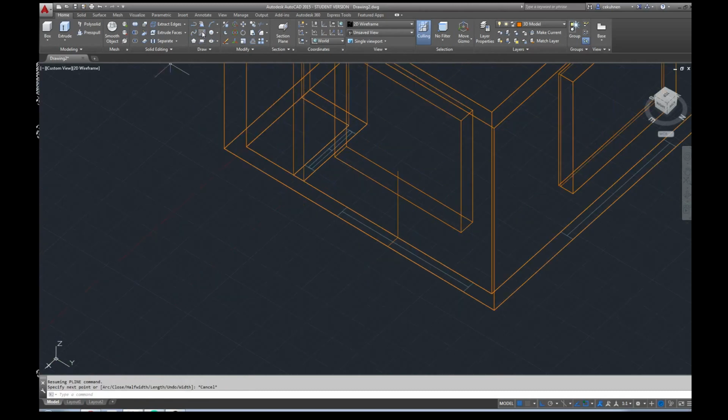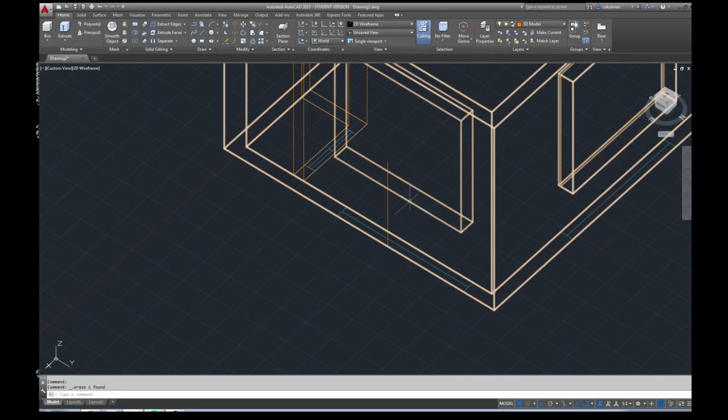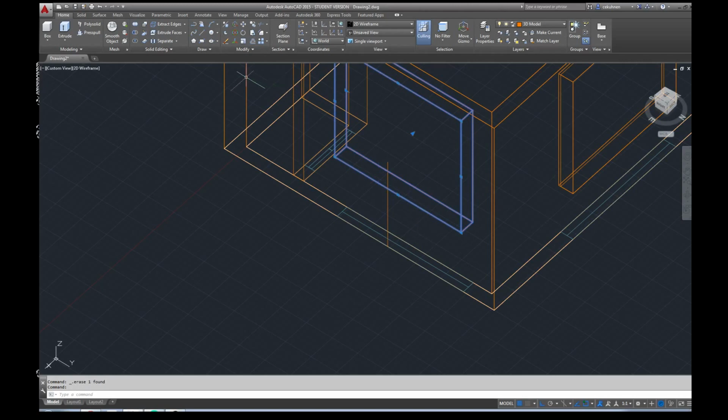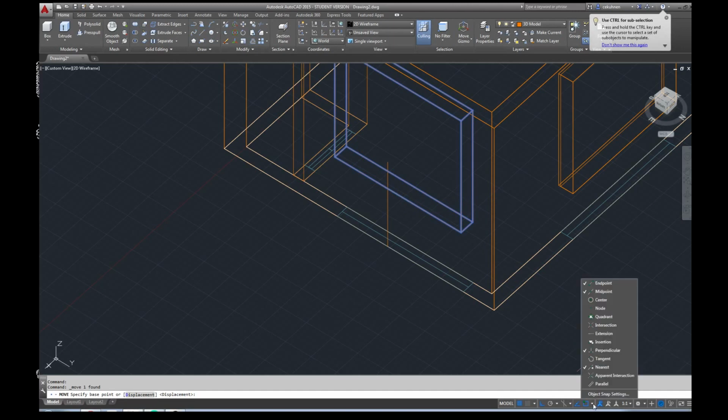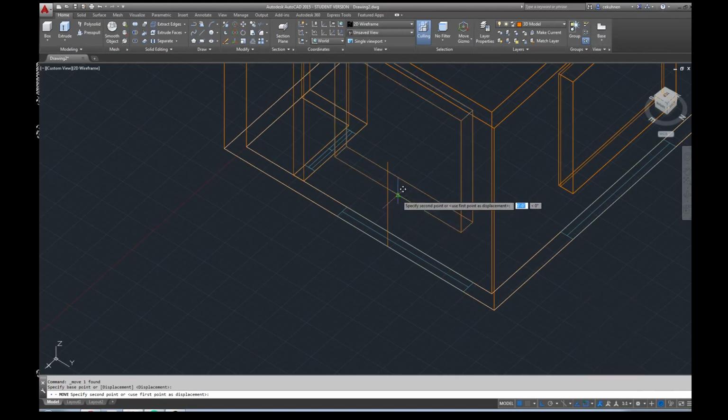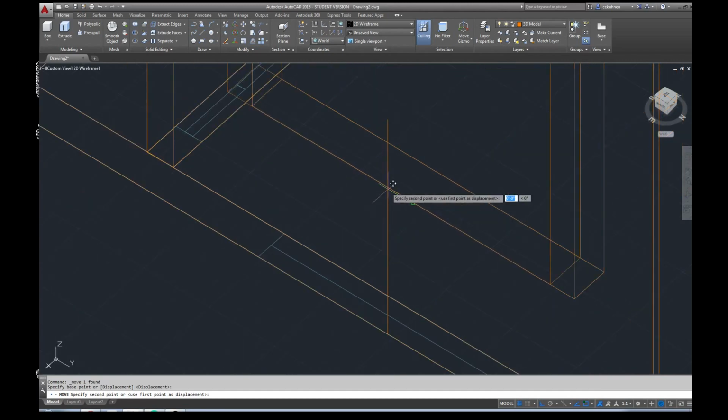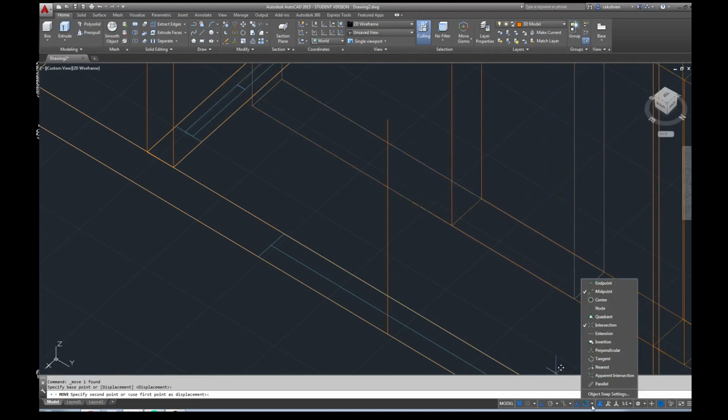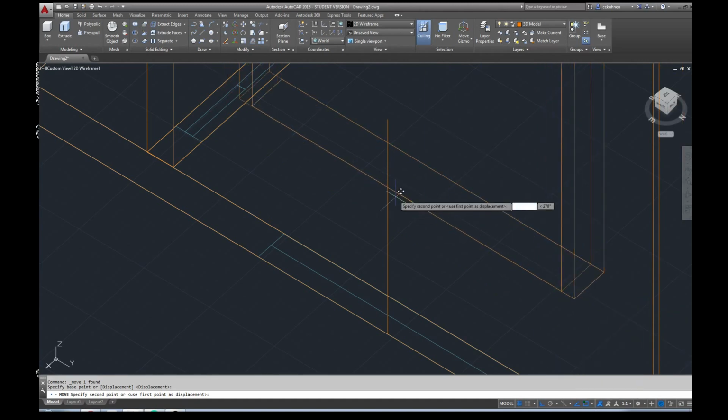Escape. And then, for example, align this point straight up. Escape. This line I can delete, because here now I can click on move. Say where's my midpoint and where does it intersect. So this midpoint, click to where those two should actually intersect. Let's see, apparent intersection.